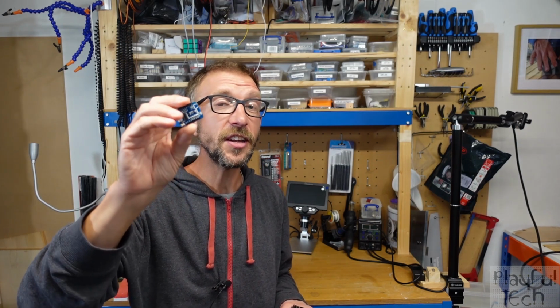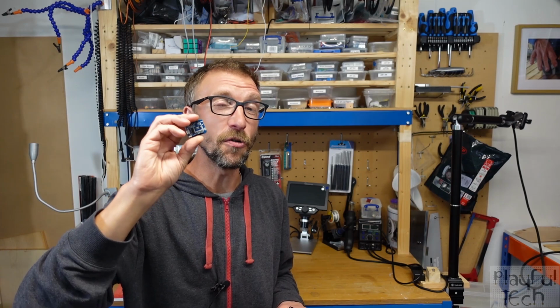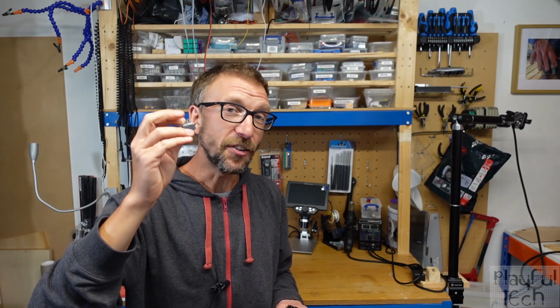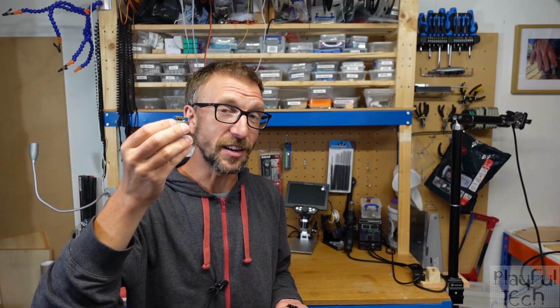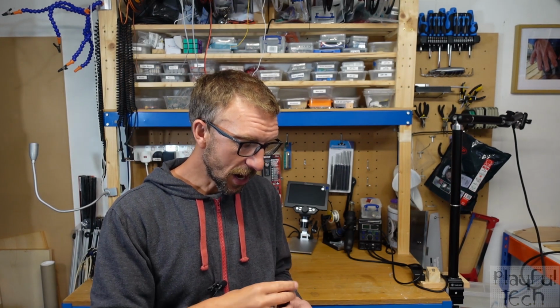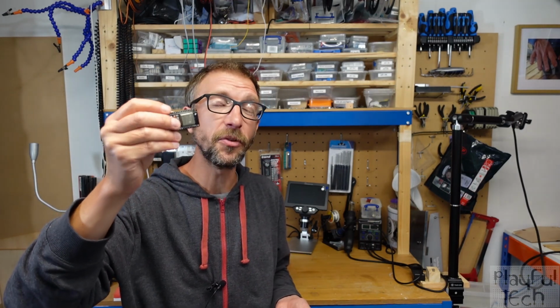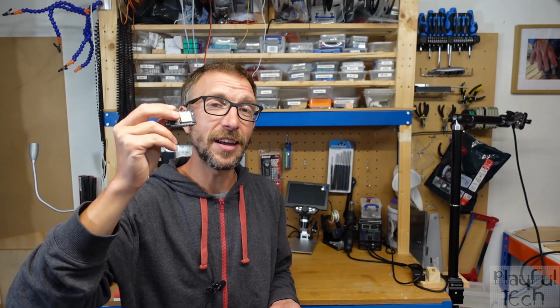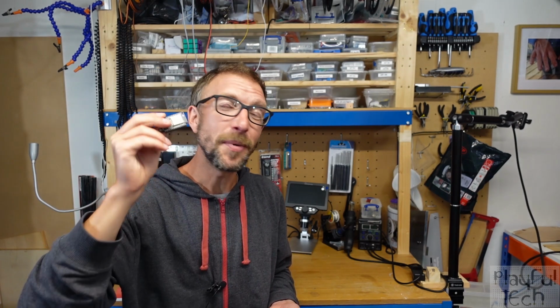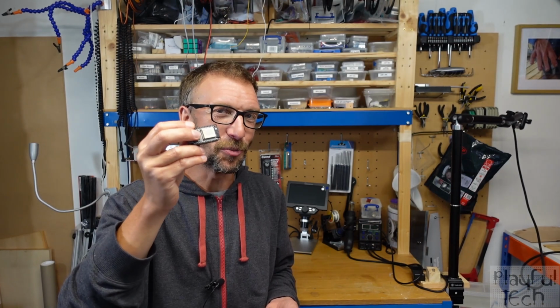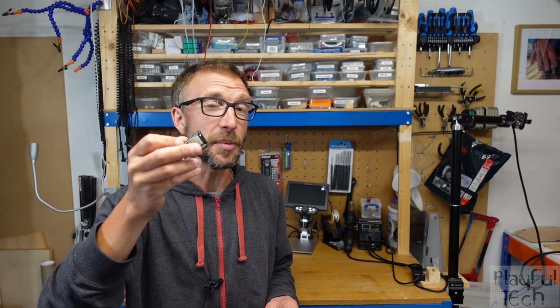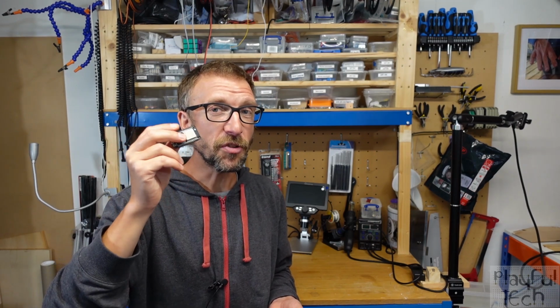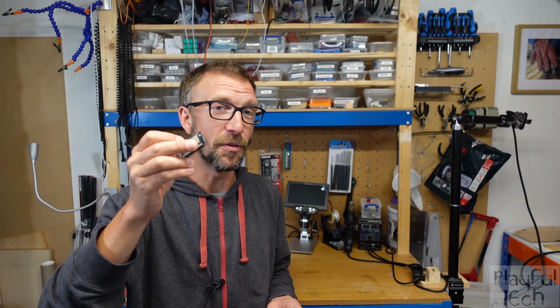An ESP8266, like this D1 Mini, has 17 GPIO pins, but you can actually only use 11 of them because 6 of them are already connected to the flash memory chip. And it's only got a single pin that's capable of reading an analog input. You can get ESP32 boards with different numbers of GPIO pins available. 30, 36 and 38 pin variants are common. But beware, even though some boards sound like they've got more GPIO pins, they too are actually already being used by some of the hardware on the board to connect to the onboard flash chip. So it's actually pretty useless to have them exposed on the side of the board.